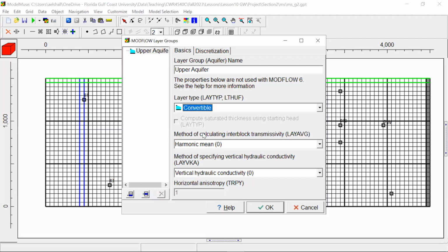Okay. And then after it solves this equation, it will calculate the head at each node. And if it finds that the water level is different than the head, then it will know that this is an unconfined aquifer, and it will accordingly adjust the head and adjust the storage coefficient. That's how it works. Because if H is variable, it's difficult not only to solve analytically, it's also difficult to solve empirically. So that's how MODFLOW will solve this equation, and if the head and the water level are different, it will adjust the head and the storage coefficient.